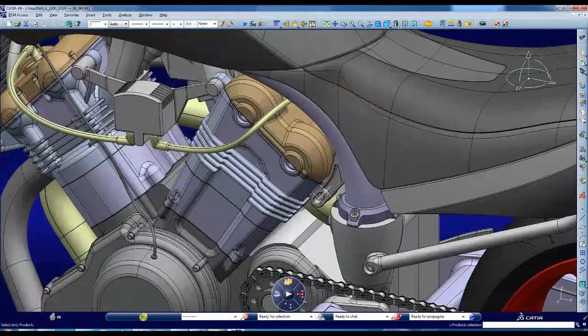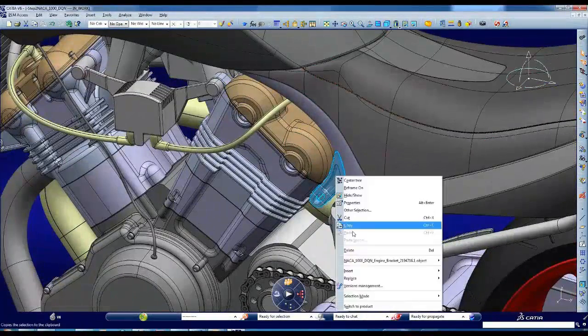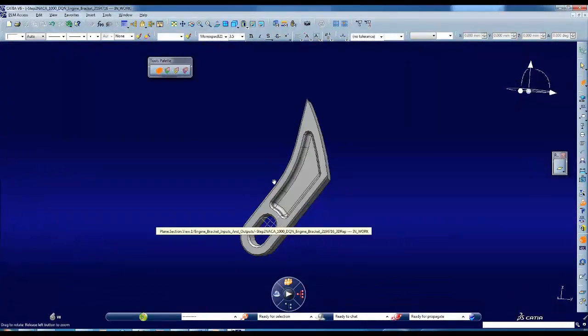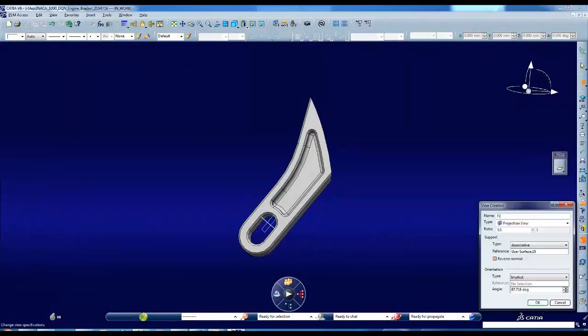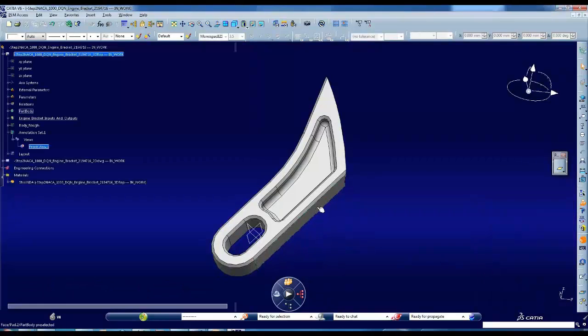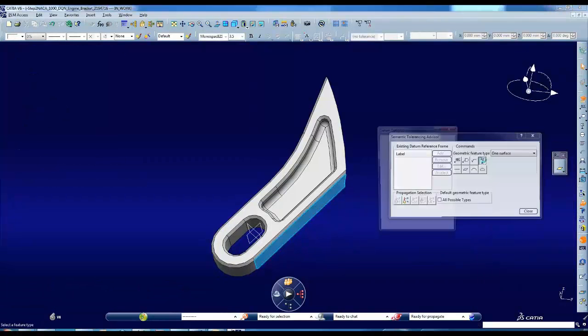We're now going to work as a detailed designer who, from the conceptual design, has taken and fully detailed the part. You can see all the filleting, drafts, pockets and chamfers which complete the geometry. Now in 3D with this single model, we're able to define views and create, based on this view definition, for example, datum feature references.